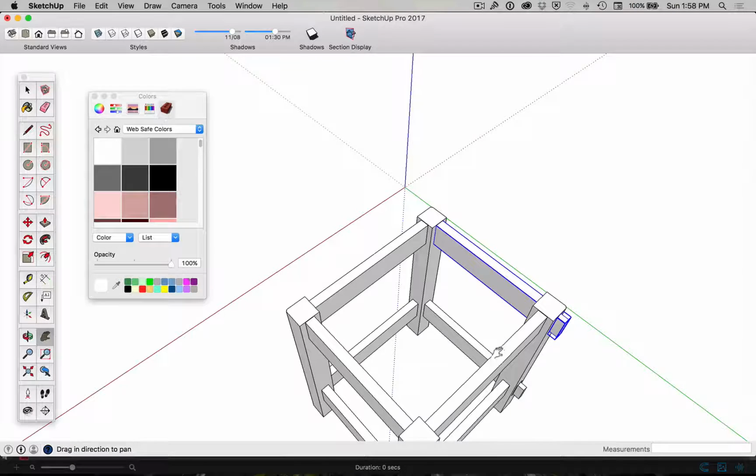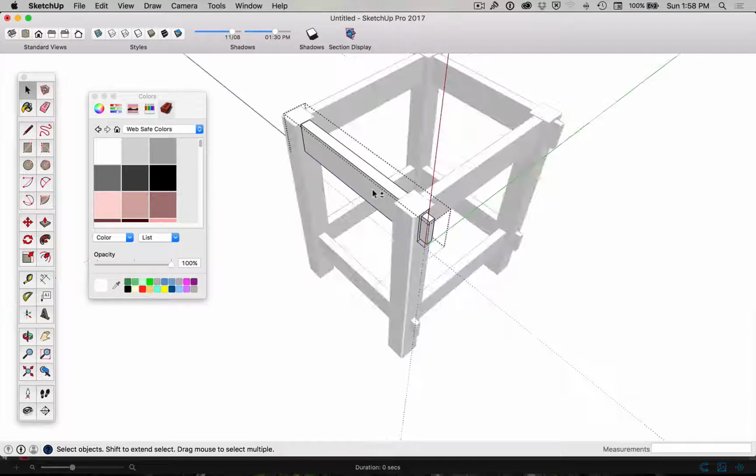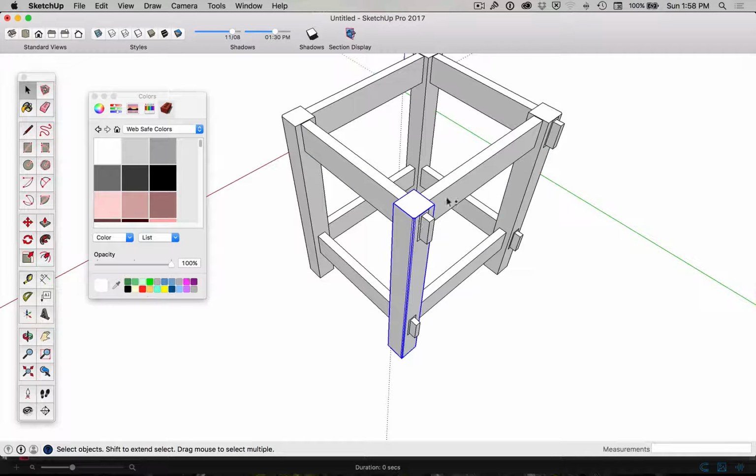All I need to do, let's just select these guys. Oh, by the way, selecting multiple things, really important to know. If I click and then hold Shift, notice how I get a plus symbol or a minus symbol. So I can shift and click that and click that and click that. So now I've got the 4 parts. I'm going to move them out. But let's say I accidentally click something else I don't want. I just hold Shift again and click it. So you can, whoops, don't click too fast. So you can see I can just unclick it, click it, unclick it.